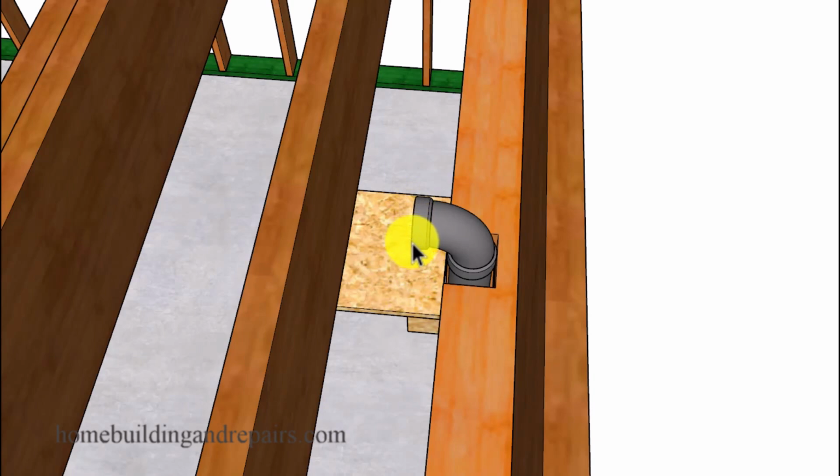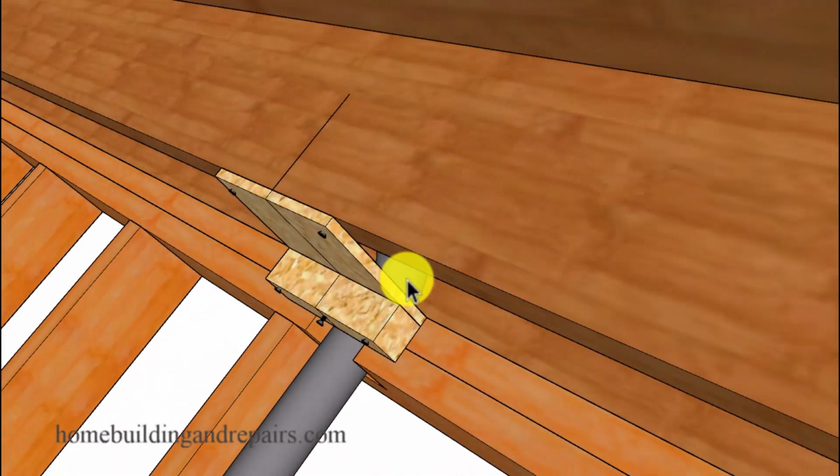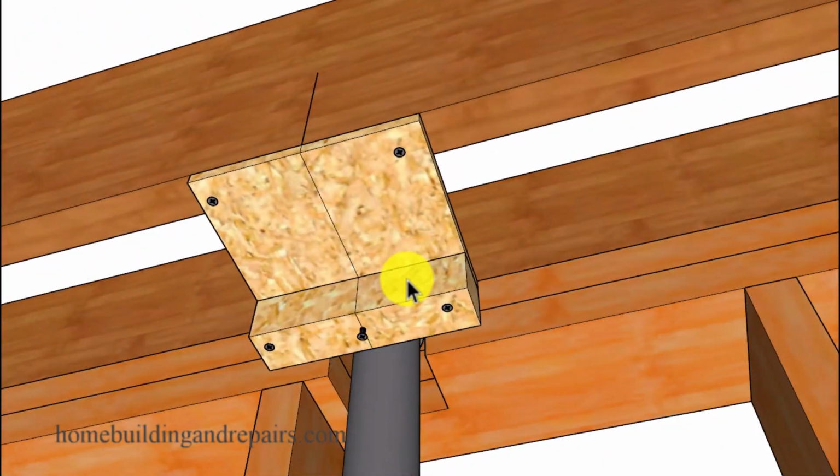Same distance as the block thickness, because this is where the slope of the pipe is going to be starting from. And keep in mind that this method will be reversed if the pipe drain is going in the opposite direction. For example, this pipe is going to be draining towards this drain pipe and therefore sloping towards this pipe.